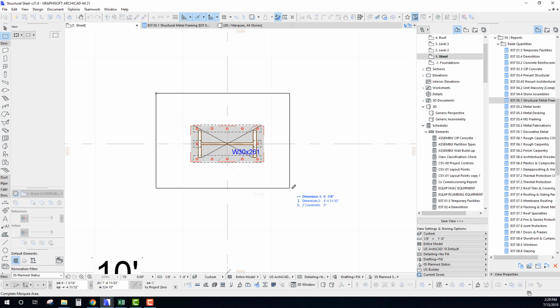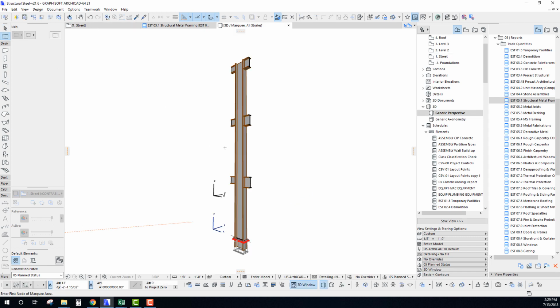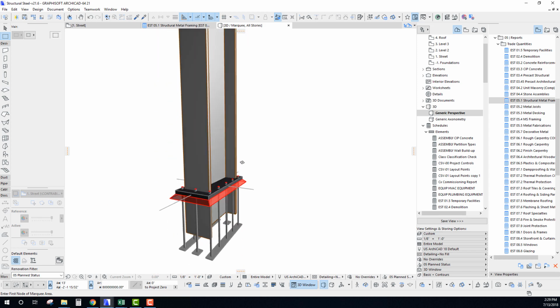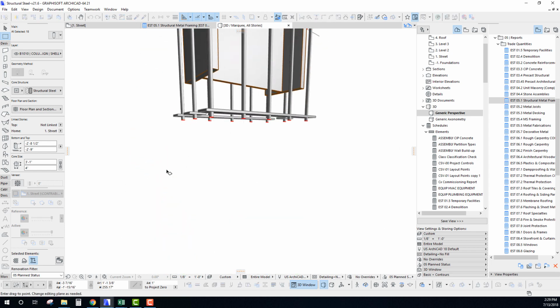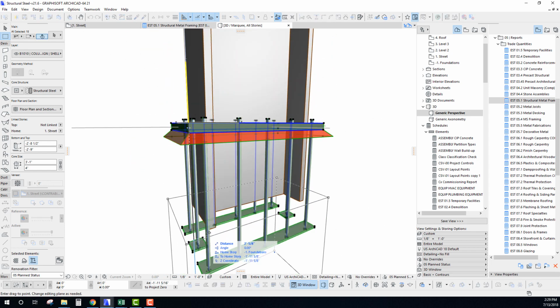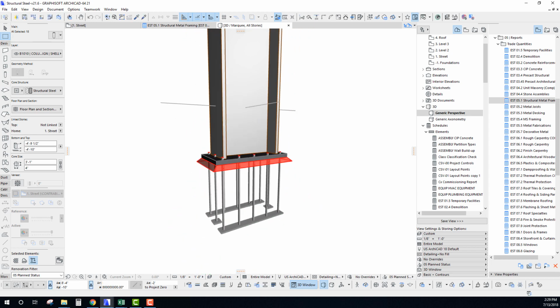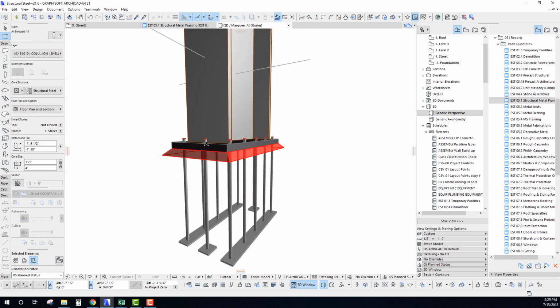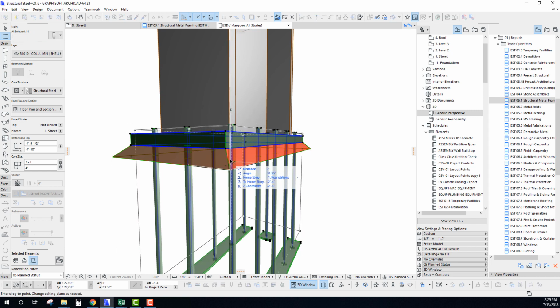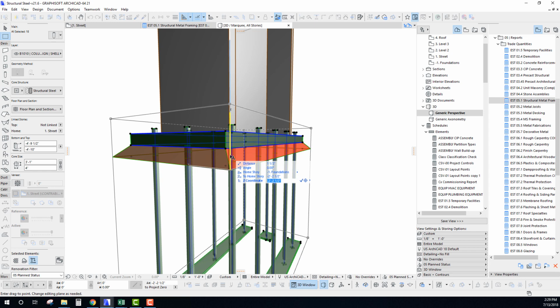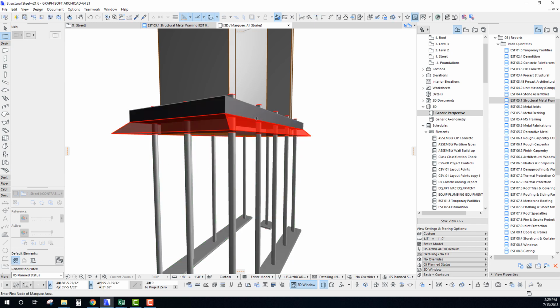So next thing here is I probably want to take all of this and adjust it so it's at the correct height. And so, yeah, we can see here that obviously a quick adjustment is needed. And depending on what the footing height elevation is, that's what I would set this to. But in this case, I'm just going to snap it right there, and that's probably fine. I could actually change this. Say if 2 feet was the top of our footing, maybe I could take this and adjust it up. So I'm going to go to Z, so I'm going to go -2 feet. So that would be essentially setting the top of our footing at the bottom of our grout.